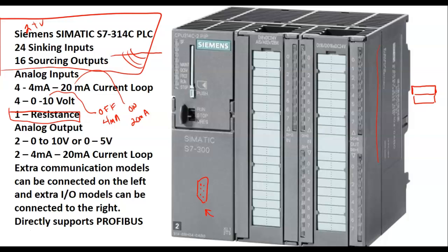And then we network them by using what we call a daisy chain, and we might get into a little networking in here. I don't know, depends on what we have. So we put a connector on here. And in the other class, y'all saw this. It has another connector that mounts on top of this, and then it daisy chains down to the next module, down to the next PLC, and the next PLC. So it's what they call a bus topology, but it's a daisy chain topology, where we can actually network the PLCs together.